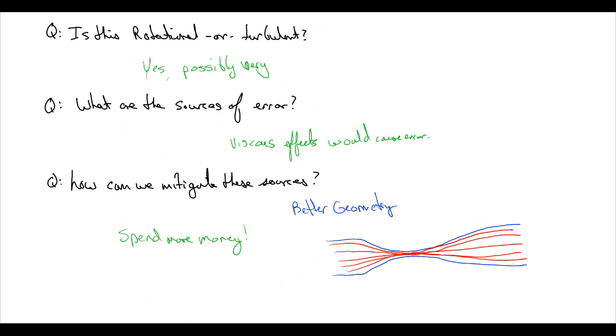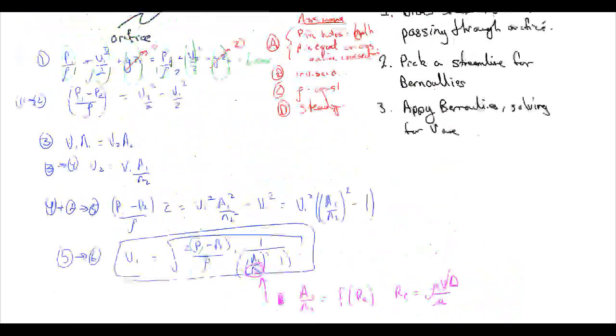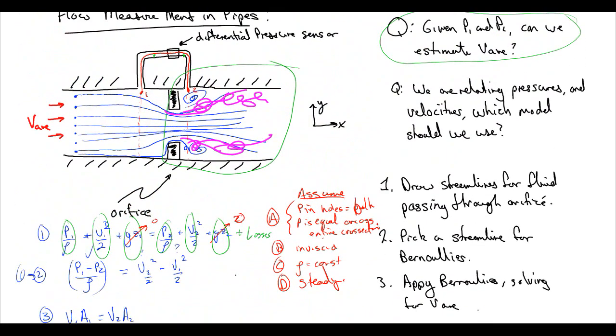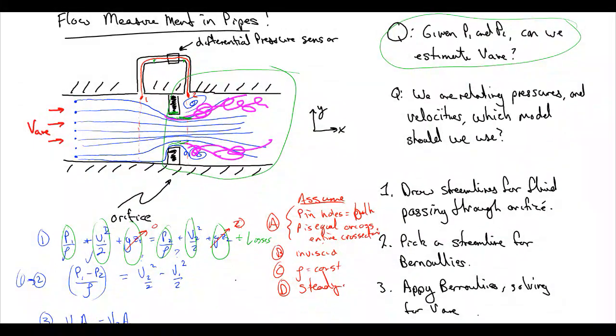We know the area here. So we could put a pressure tap here, and put a pressure tap here. We know A2 and we know A1 very well because they're constrained by the geometries of the system. The reason why we can't actually use the diameter of our orifice here, by the way, is because the water tends to overshoot the orifice and actually create a smaller diameter than the orifice requires. Again, water can't go around a 90-degree bend. So it overshoots it, and the area here is actually smaller than the area you might expect.